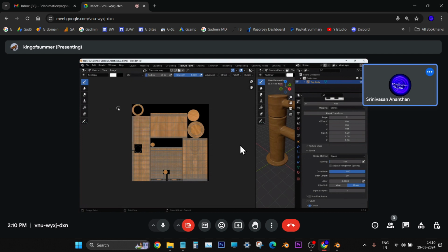The first time you are doing it, save is okay. Now we choose 16-bit inside the textures folder, 16-bit with compression 0. So we have to save the texture, whatever we are painting, separately.